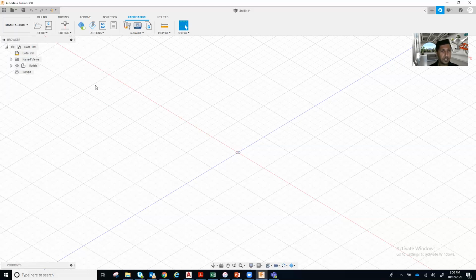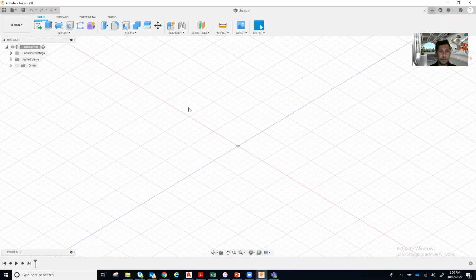All right. So let me introduce you to the Fusion 360 user interface, starting with the toolbars. You have already noticed on the left top corner what you can see here, this is the browser. So everything you create, whether you create a model, a component, construction planes, or axes, every single thing will be displayed in this browser. If you're working on an assembly, with multiple components and sub-assemblies, every single component will be listed on the left side inside this browser.